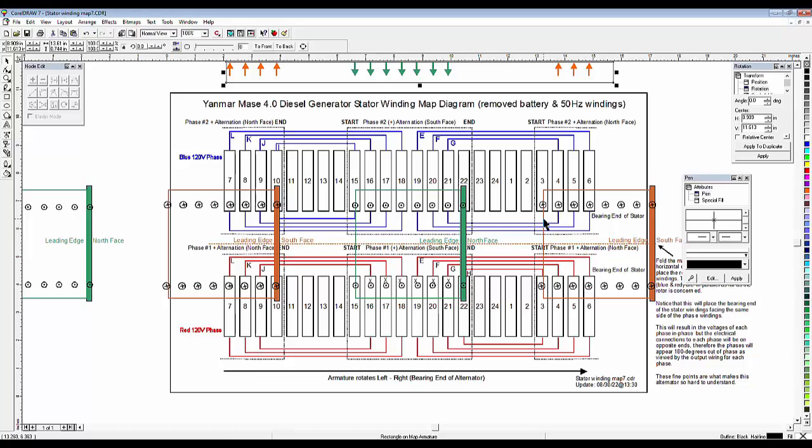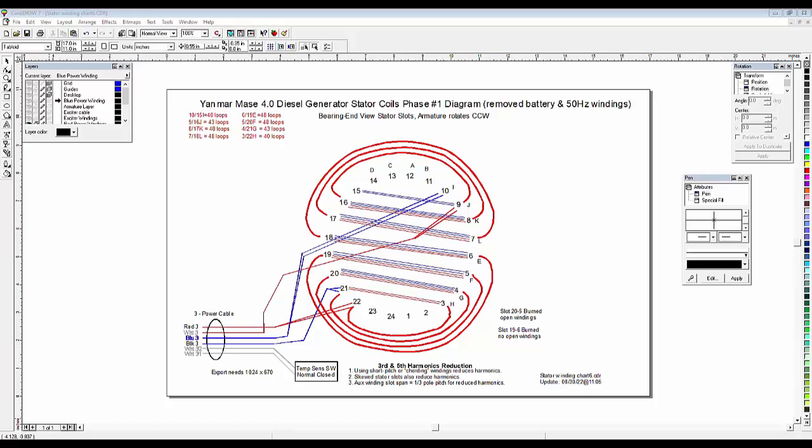these windings together. One last thing that needs your attention here is the fact that this end of the windings in slot 16 and this end of the windings in slot 9 are not directly across from each other. They're all set by one slot. That allows us to jumper over to the next winding. So if this went back to 15, then you couldn't jump over to the next one. So this one side of the winding in slot 9 goes over to slot 16.